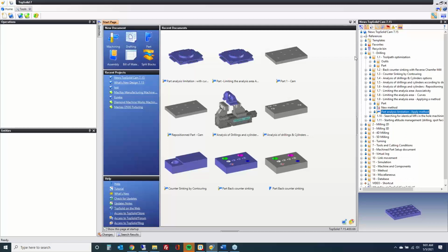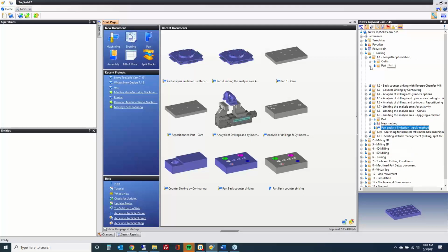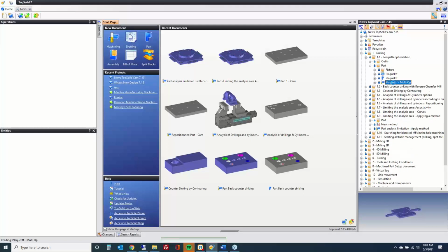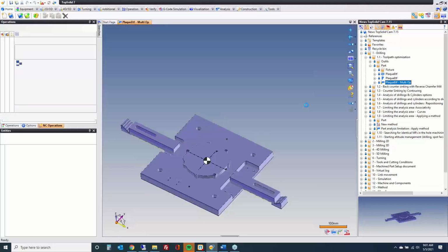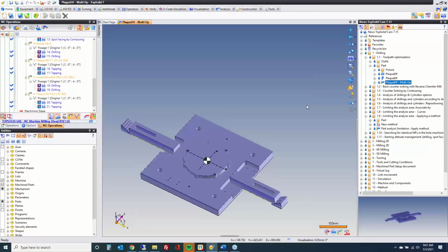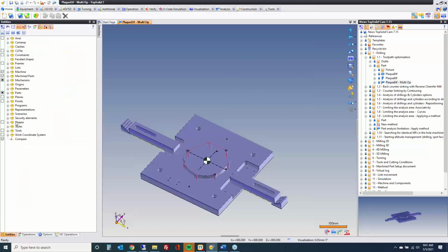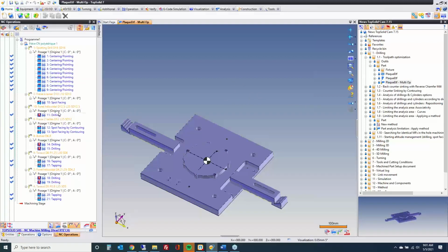So improvement number 1 has to do with toolpath optimization for drillings. Reorganize some things here. So rule of thumb, all of the drillings that you're going to optimize need to be the same primitive, same tool, same work coordinate system, same part.